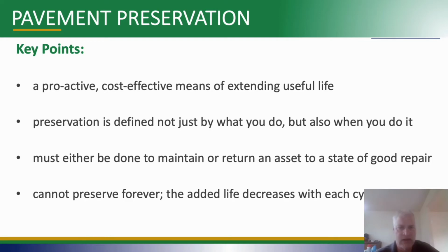So some key points to what that shows. Preservation is a proactive, cost-effective means to extend life. And it's not just defined by what you do, but also when you do it. You're trying to maintain or improve condition, but not necessarily repair severe distress. And you can't preserve it forever. You're going to get added life that's decreasing each time you do a cycle.